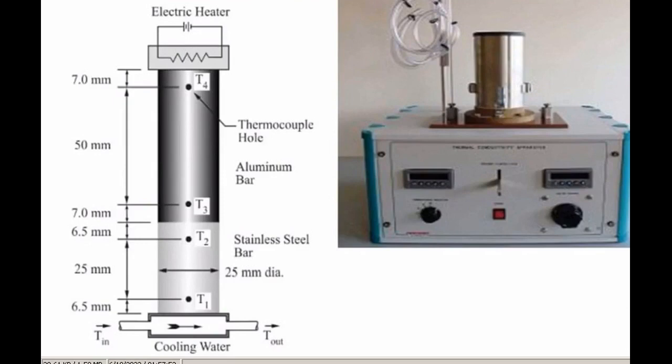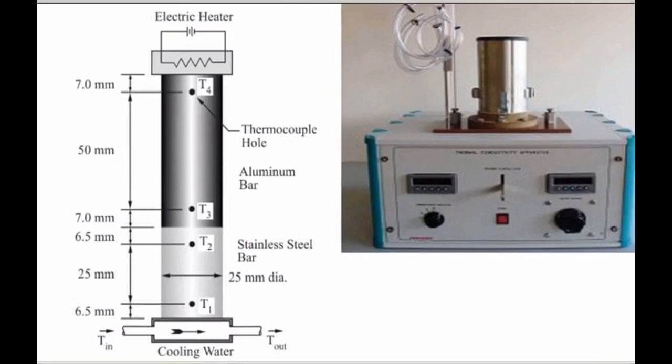Now what do we do at the second attempt? By using that regulator connected to the water outlet line, we block the water outlet flow by turning it. With respect to the previous scenario, we have now blocked the water outlet line. So what will happen to the time taken to collect 200 milliliters of water? In the second attempt, the time taken will increase with respect to the first attempt, because you have blocked the water outlet by using the regulating valve.